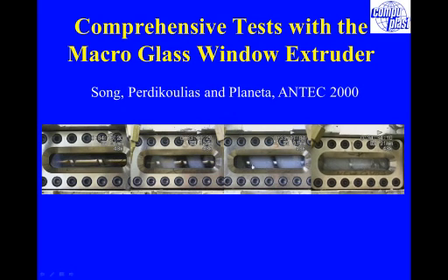And then somewhere right here, you'll start to see a little bit of melting. It's more clear over on this screen. That clear area where you can see the screw doesn't mean that it's empty. When the polymer melts, because it's amorphous, it's clear, so you can see right through it, and you can see the root of the screw. Also, here you can see the flights on this side, but over here you see a little bit more of the screw, and that's the melt pool that's being generated. That material continues to melt, and the solid bed continues to get narrower until ultimately it disappears.